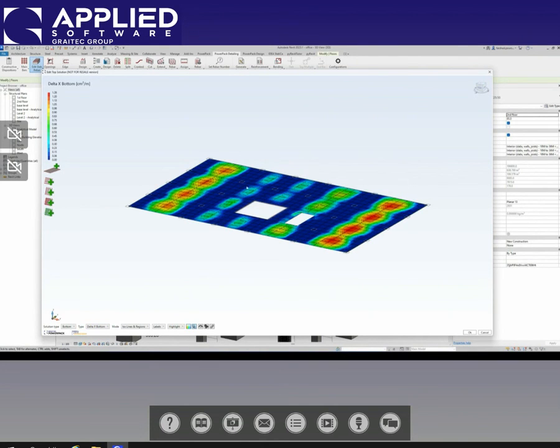To do that, we can add different zones. So you can put your rebars based on different zones, or you can select the full slab. In that case, I will just select the full slab, and I will put my rebars in both directions. So you click there, and now I'm going to be selecting my zone. In this case, I will select full slab.